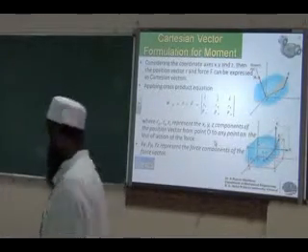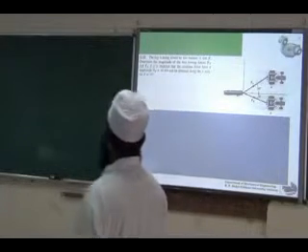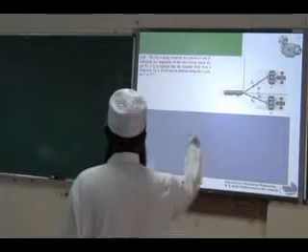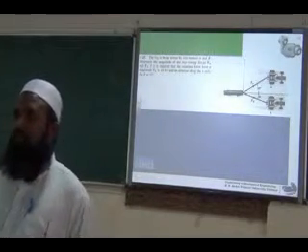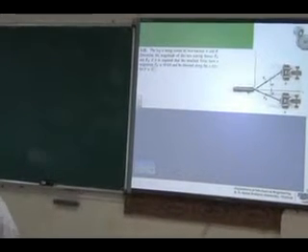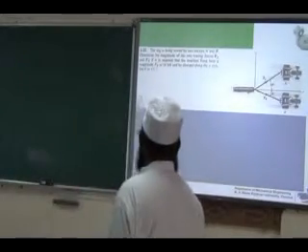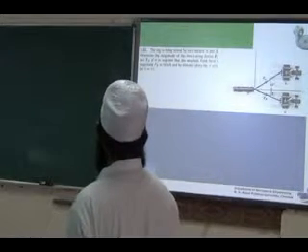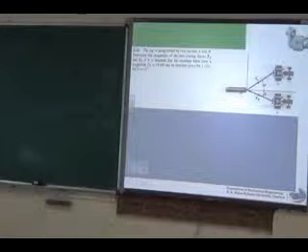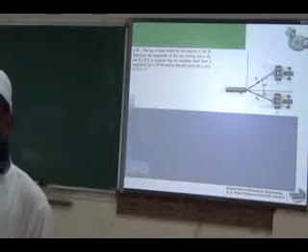Okay. So this is the first problem we are going to see. There is a log. It is pulled by two tractors. The resultant force is given, and the angle theta is also given. The same problem we did in another exercise, isn't it? Do you remember? The two boats, they are pulling the log. We did the same problem, but in order to have more exercises, I am giving this exercise. So how will we find out forces FA and FB? Resolve the resultant into two forces FA and FB. In simple cases like this, you can use the cosine rule or sine rule or parallelogram law.